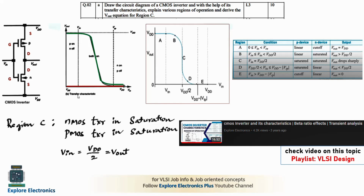Why? Because when the input Vin reaches the threshold voltage of the N transistor, initially the N transistor is off, and now it starts to turn on. When it starts to turn on, a discharge happens through this path from the output terminal. That's why the output keeps on reducing, and finally it becomes 0 when the input reaches the maximum value VDD. So that's why it is a smooth curve like this, and we can divide it into regions A, B, C, D and E.